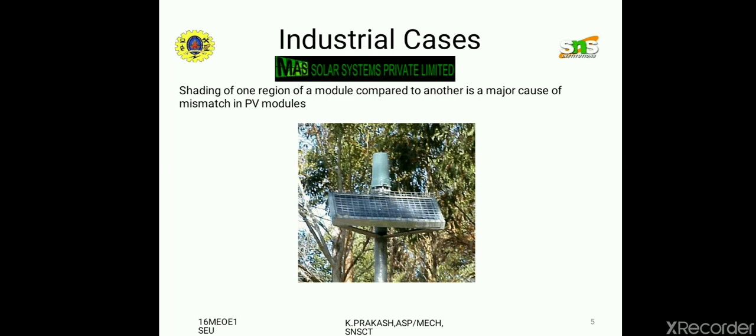This is how temperature plays an important role in photovoltaics and in designing solar PV systems. Because of this temperature difference, the open circuit voltage decreases with temperature. The power production efficiency of the solar panel will drop when the panel reaches that particular temperature.